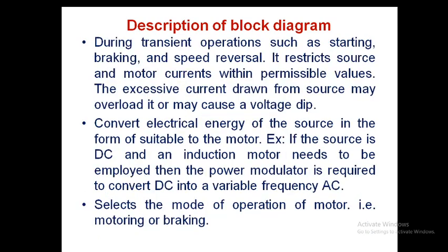And the next one is during the transient operations such as starting, braking and speed reversal. The starting of the motor, braking of the motor and the speed reversal of the motor are called the transient operations of the electric drive. During these operations, it restricts the source and motor currents within the permissible values.